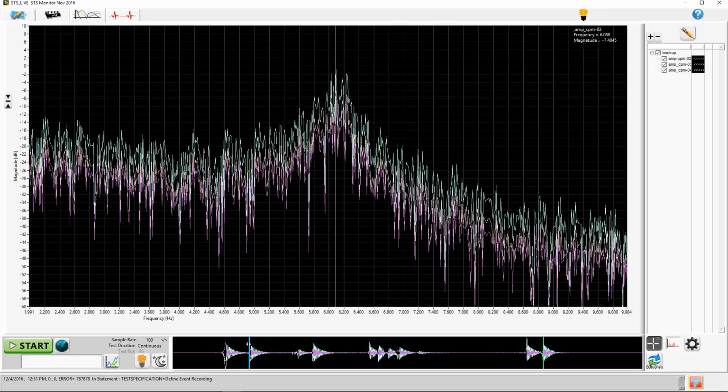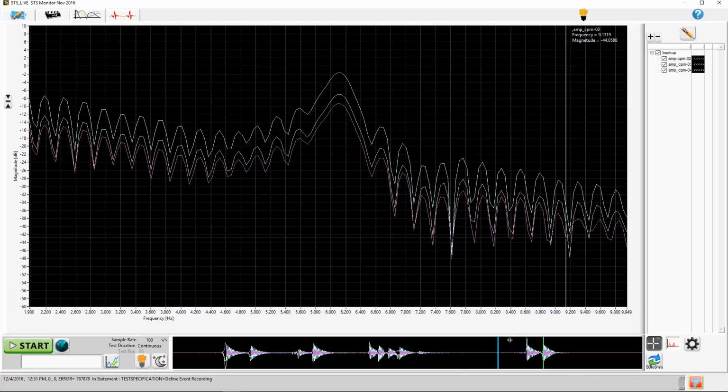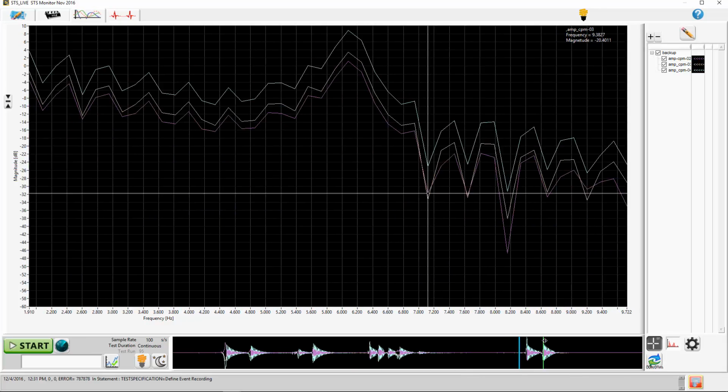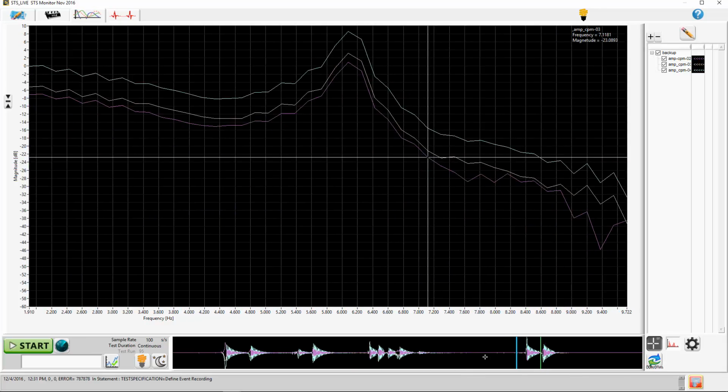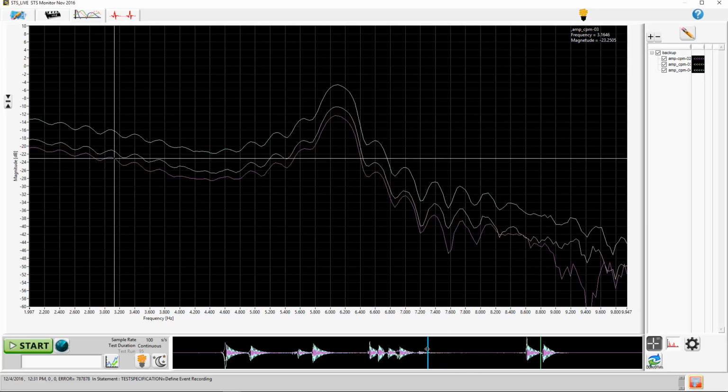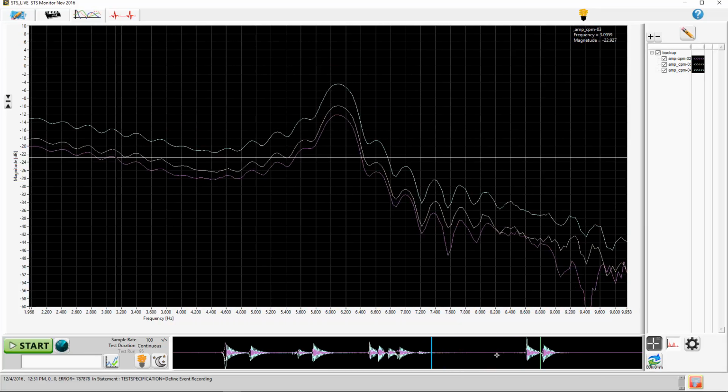We want to see with high resolution what the resonance was. Okay, we can do that, but the resolution is now too low. If we make the time record longer, we get a better resolution. But there is not much frequency information there, so the magnitude is dropping.